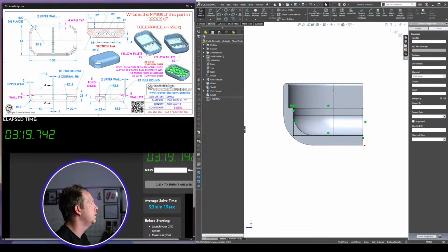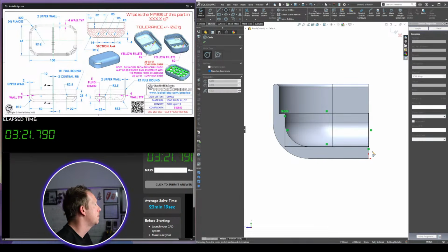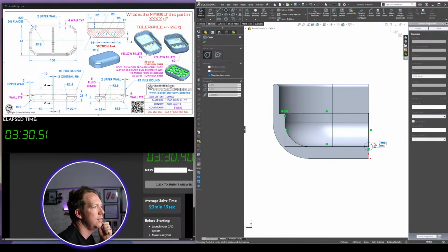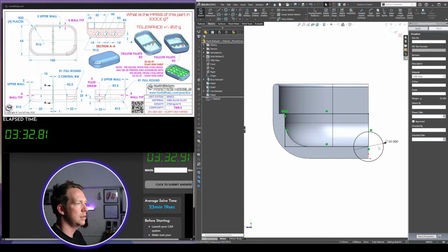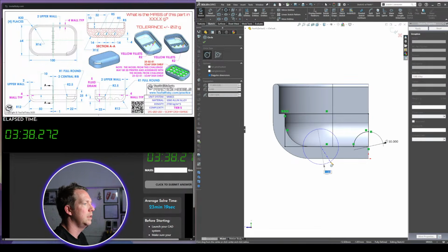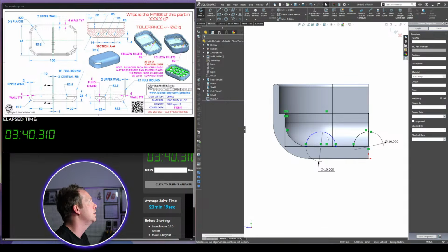We're going to put then in a hole. Just looking for the hole detail. So it's a semicircle that has a radius of 5, so it's 10 like this. Can just trim that. I need to put the next one in as well. Another one. And the distance apart is 14.